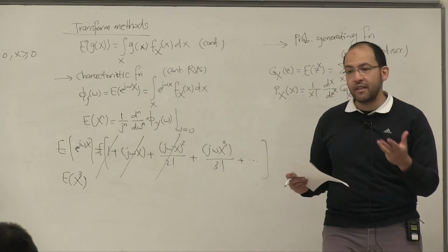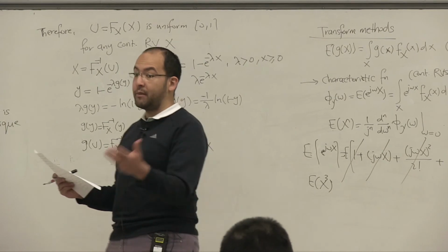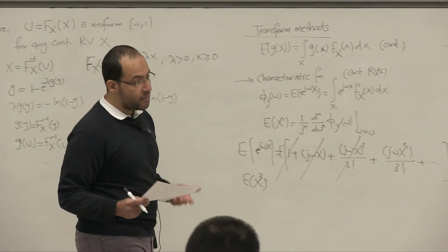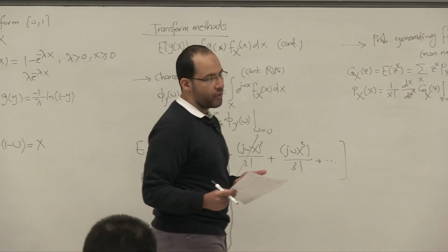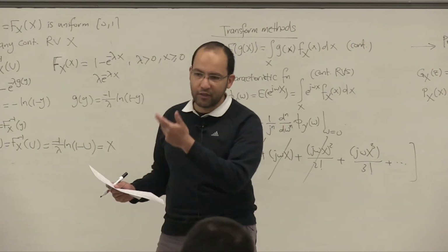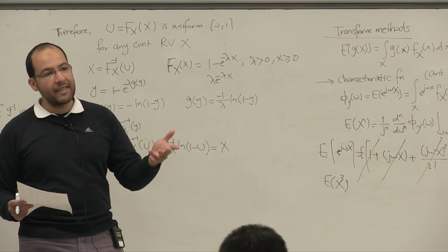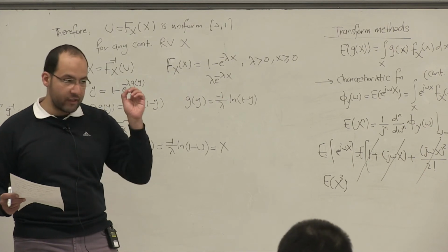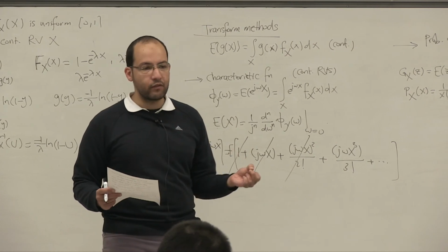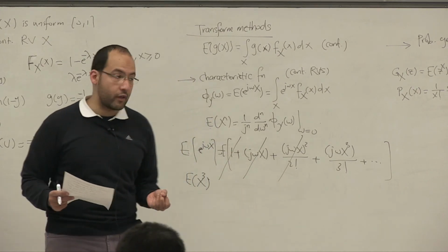So only if the time domain signal is periodic, that discrete time domain signal is periodic, would we have its DFT. It's the discrete time Fourier transform. It's the DTFT, not the DFT, because the DFT by nature operates on periodic discrete signals anyways. So only in that case will the discrete time Fourier transform end up giving you a discrete function. Periodicity in time results in having a discrete function in frequency.